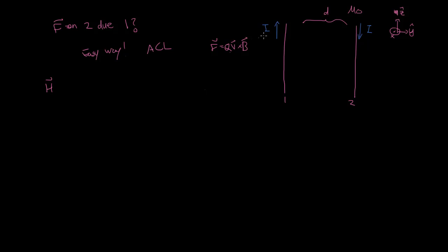You had two integrals, a couple cross products. It was really ugly. So I said that in many cases, if you have two currents involved, the way to go about it is to find the magnetic field for one expression first. If you have a simple expression for the magnetic field, then you can plug it in and approach it. You have one less cross product and one less integral to deal with. So we're going to find H first.